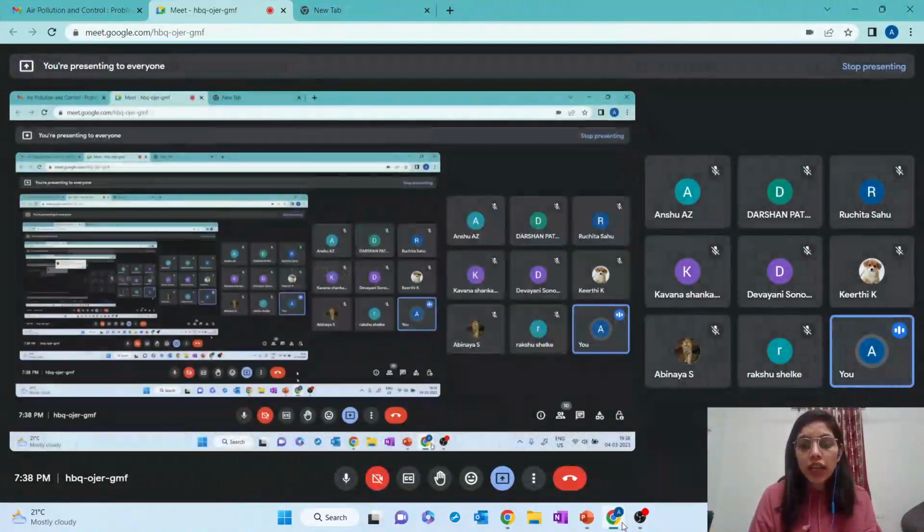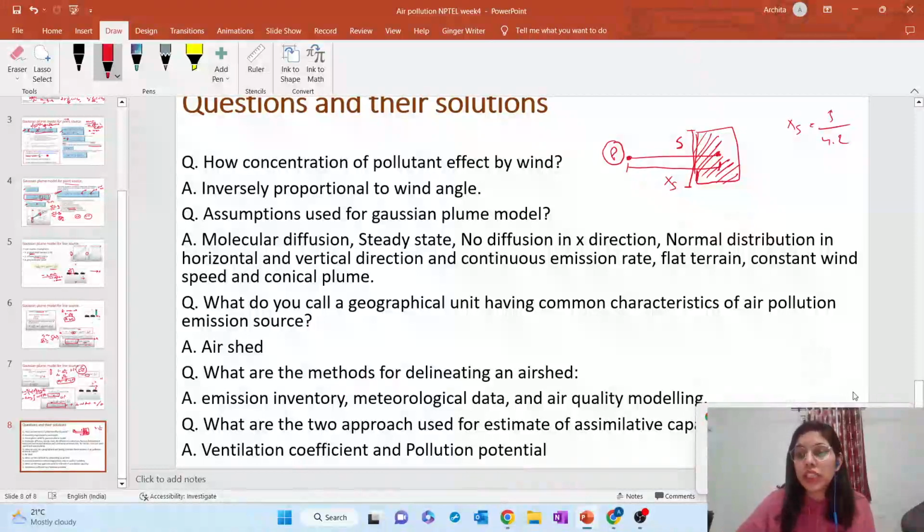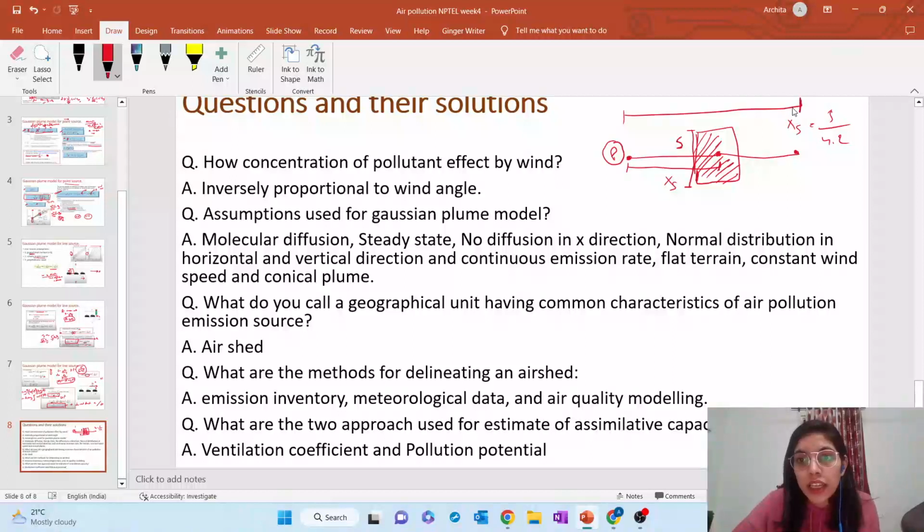And once you do that, you have to calculate the entire region it can affect. So you have to extrapolate it here, which is, if the point is here, you see how much total area it can affect at the far off point, and you measure the Gaussian plume for this point using the same equation that we have calculated for the point source.